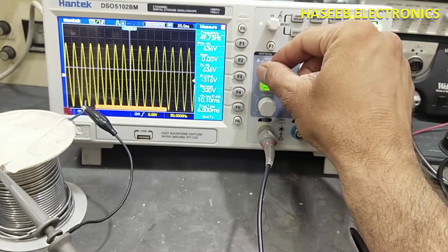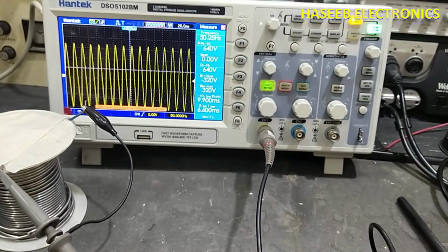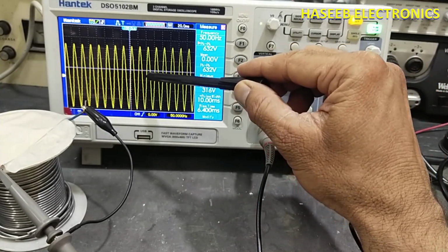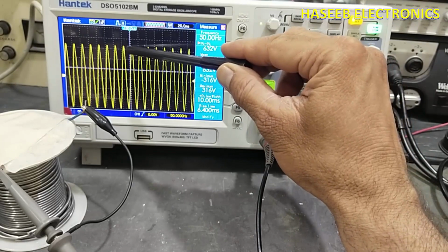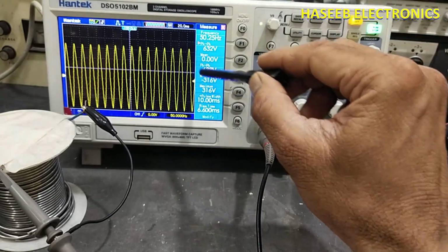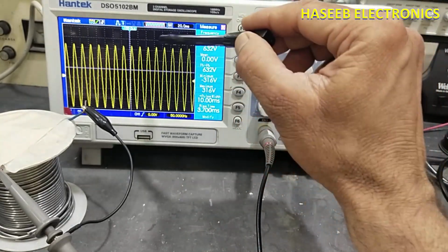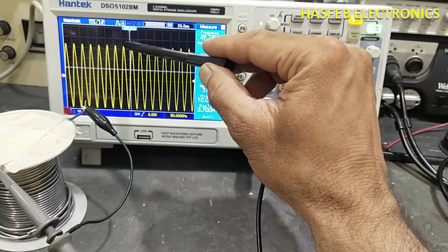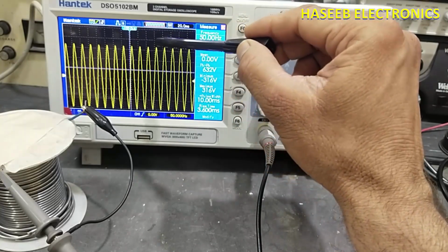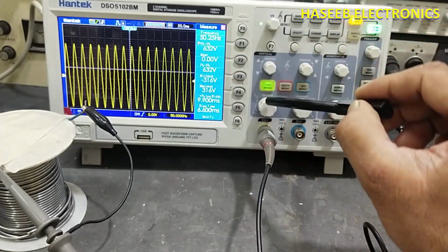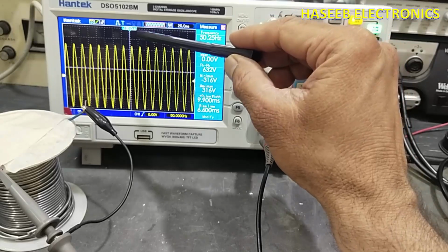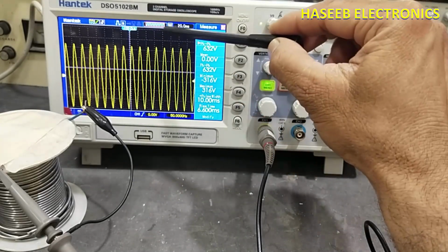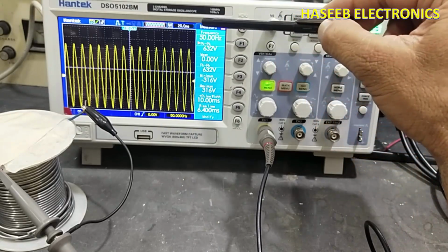Now if you see here, we have 1, 2, 3, 4, 5, 6 and 5. 6.5 multiply 100, 650 volt, and we have 1.5 grid as a spare headroom for more voltage. So 1.5 multiplied by 100, we can test 150 volt more. We have space to test more 150 volt until the level will reach 800 volts.